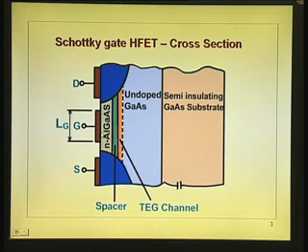So, all that you write is the charge here is gate voltage minus V off into the capacitance of this layer. In fact, that would include the capacitance of the doped layer and this undoped layer. This undoped layer must be kept as small as possible, but it is needed so that the electrons here do not see the dopants. The electrons are not in the vicinity of the dopants. So, the Coulombic scattering is removed by putting the undoped layer here.